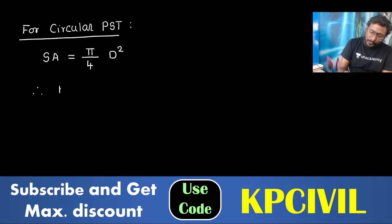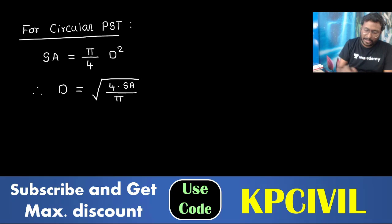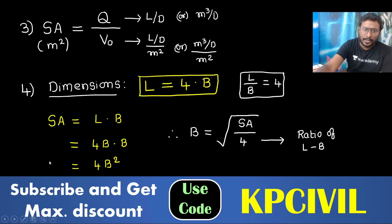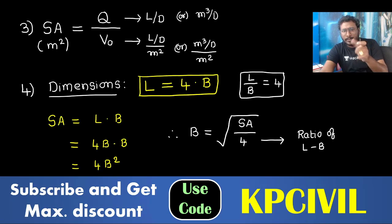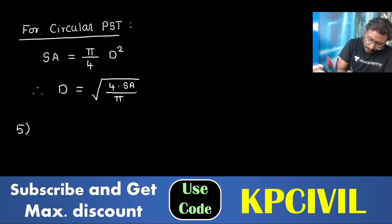So what is d now? D is equal to under the root of 4 into surface area by pi. Capital D, the diameter, is equal to under the root of 4 into surface area by pi for a circular sedimentation tank. Got it? Now, what about depth? Depth is important because we determined L and B for the rectangular chamber and D for the circular chamber. Depth is very important.